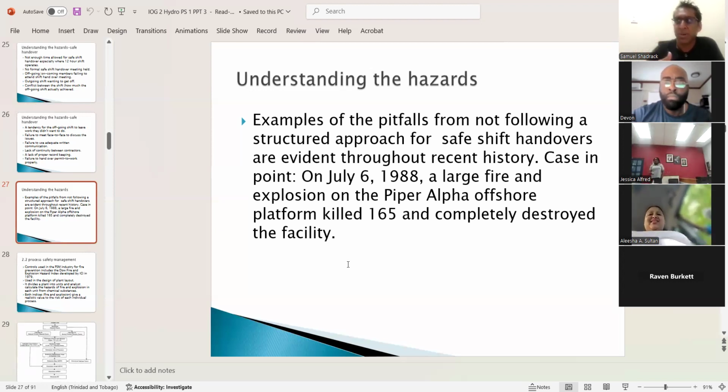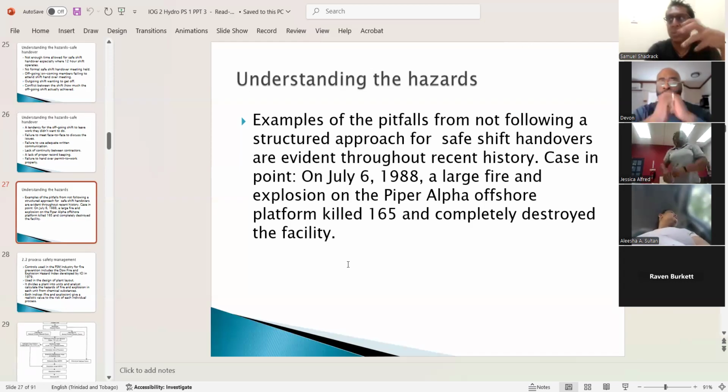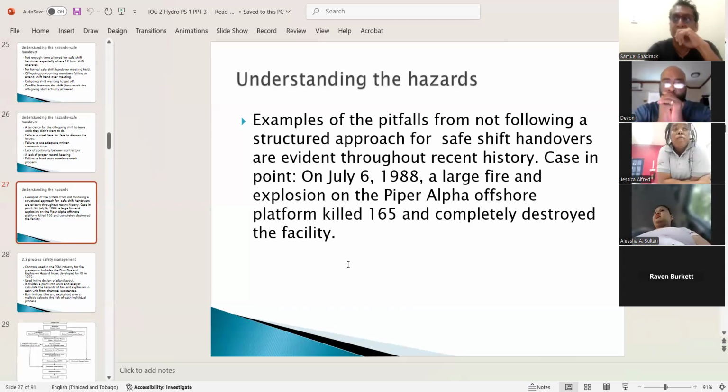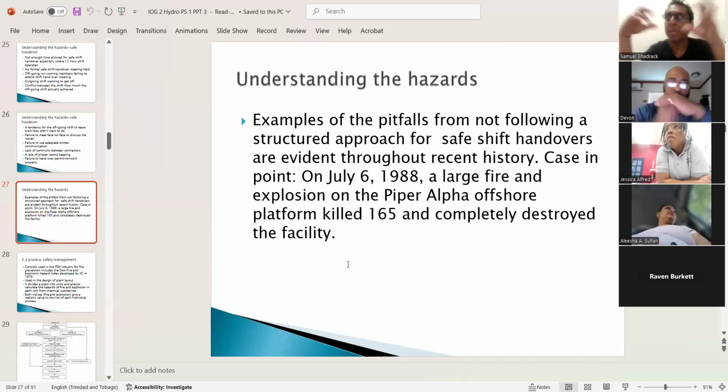We all know the story. A lot of us would know the story already, that they had a blank-off line, right? And that was on their permit. It was on the permit, just the permit wasn't handed over to the night shift. In the night, there were like two lines, and the good line failed. And so the night shift didn't know that the other line would have been blanked off. So they put on the other line, and of course, that resulted in the buildup of flammables and exploded from there.